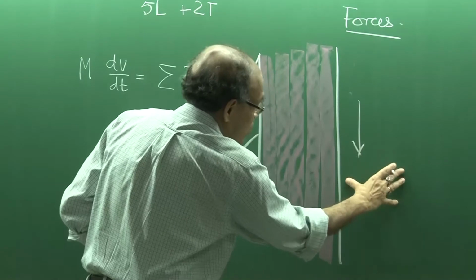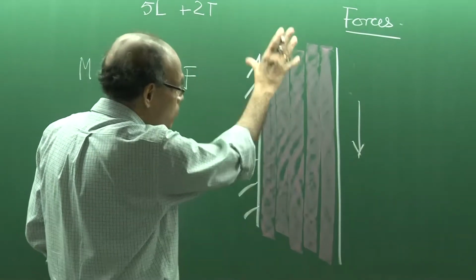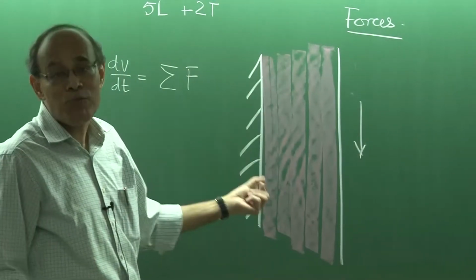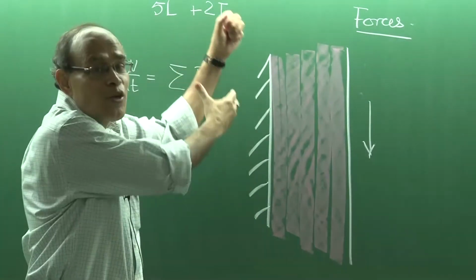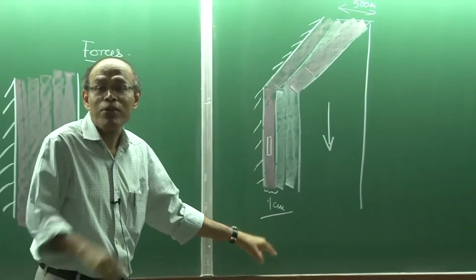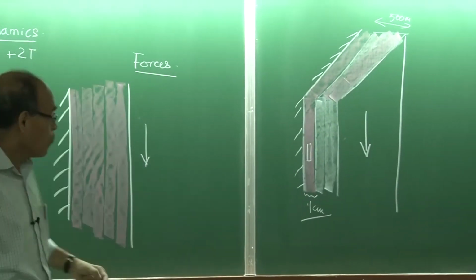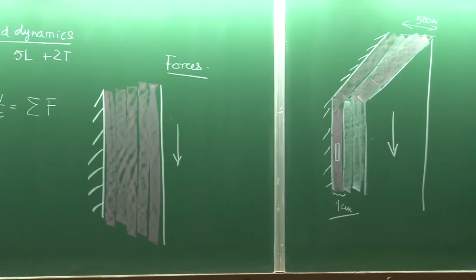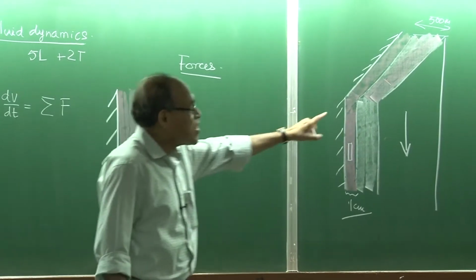even without the motion of this strand. The powder or the molten powder will tend to move because there is a net gravitational force acting. So, therefore, the powder continuously moves from the mold surface, it enters here, and then through the bottom surface the powder in the solidified form again will exit. It is a very complex process, but let us not bother about the intricacies of continuous casting.